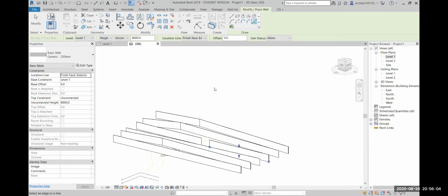Let's say you want it for creating the walls and structural parts. So what we do generally, we clear off all the unnecessary elements. I'll just keep the wall layer, I'll just keep the column layer, that's it. Only the basics we should keep. Otherwise, there's no point of bringing those heavy CAD files over here and creating chaos. So just keep it clean.